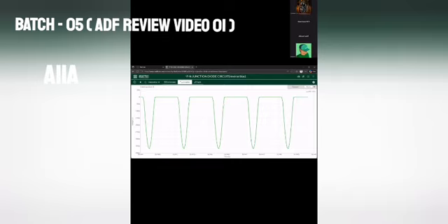In the first graph, the waveform shows that the diode is blocking the positive half cycles and allowing only the negative half cycles to pass. This indicates that the diode is oriented in reverse bias with respect to the input AC signal. As a result, the output displays deep negative voltage dips while the positive portions remain near zero. And this completes the reverse bias.